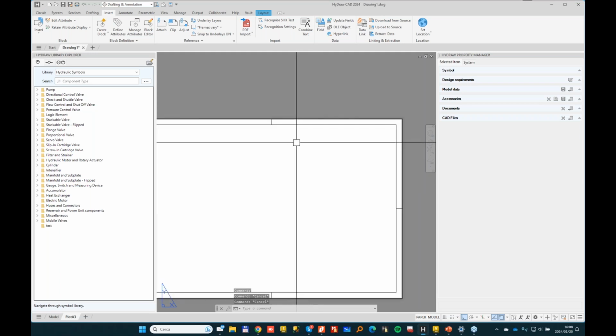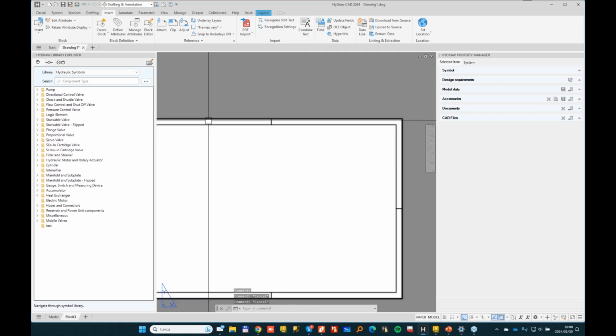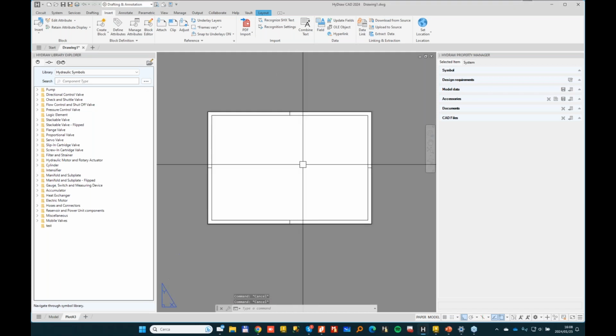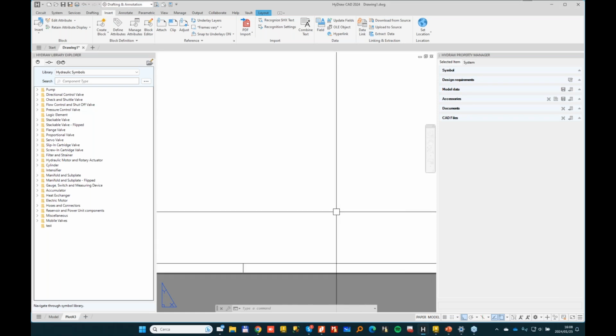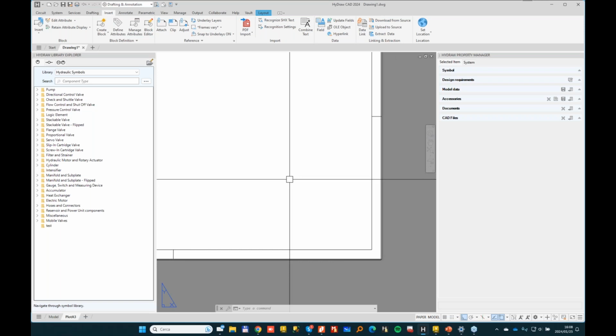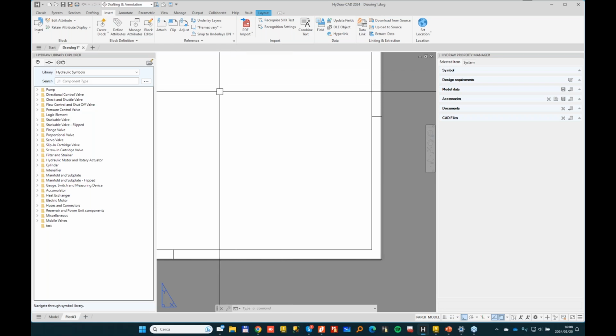Now, most of you may already know that in a block we can have attributes. Now there is nothing there. A lot of users of AutoCAD in general do not know enough about attributes. Attributes are very handy because they are controlled outside the block. So if you put a text inside the block, you will need to enter the block to modify it, while attributes can be controlled from outside and also can be controlled by a PDM system, for instance.